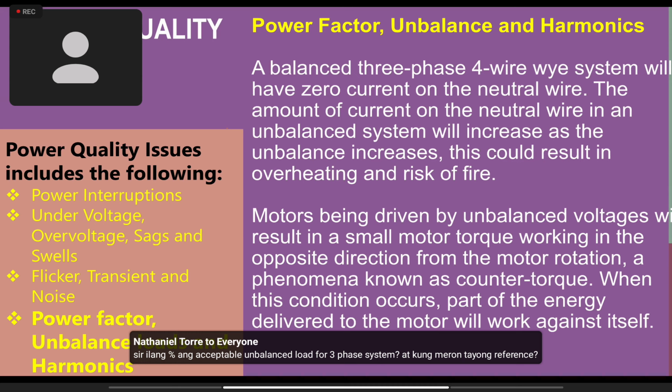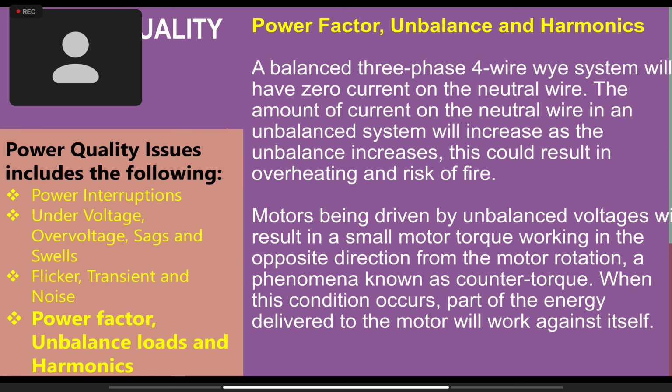So that's why it's very important that after commissioning our electrical system, kailangan talaga mag-load balancing. At least to minimize, not to eliminate, kasi imposibleng ma-eliminate ang unbalance, but to minimize the range of the unbalance in its phases so as to limit the amount of current flowing to the neutral.